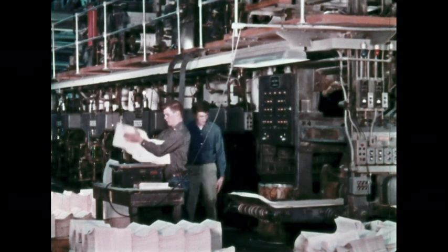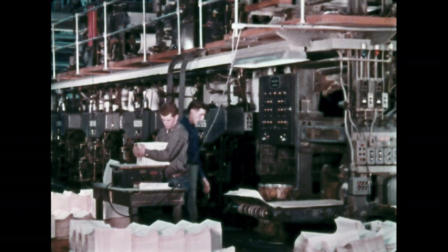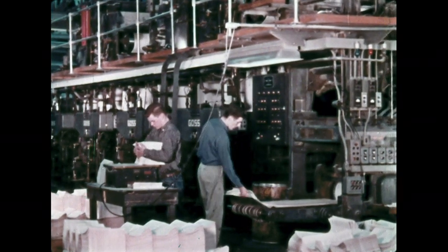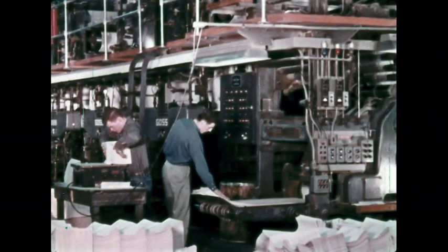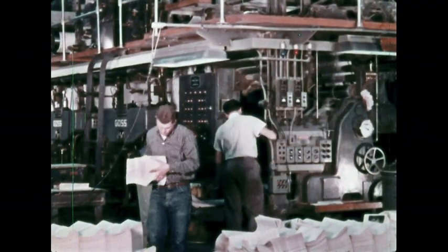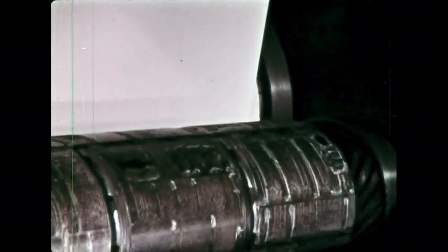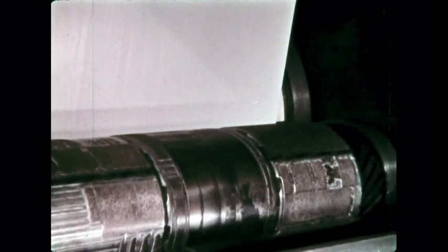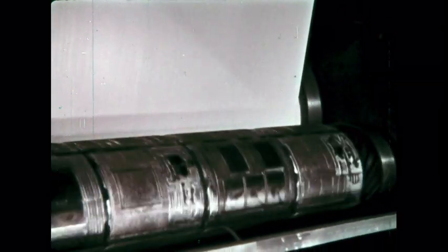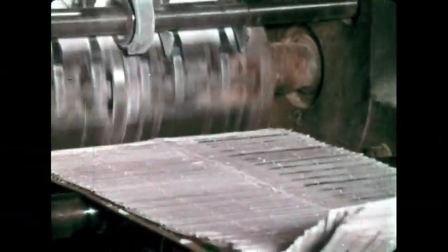The rotary cylinder press, still another basic type, differs from the platen and flatbed cylinder presses in that both the printing image and the material on which the printing is to be done are carried on cylinders. Thus, in addition to an impression cylinder, this press also uses a plate cylinder. These cylinders turn continuously, pressing the inked printing image against the material as they turn, thus continuously reproducing the printed images.